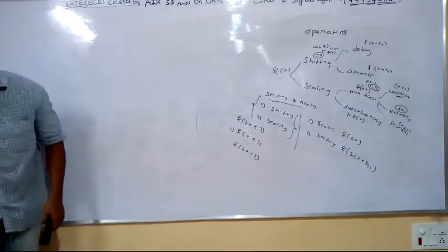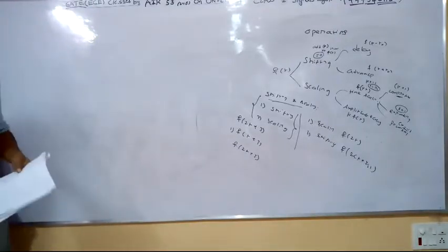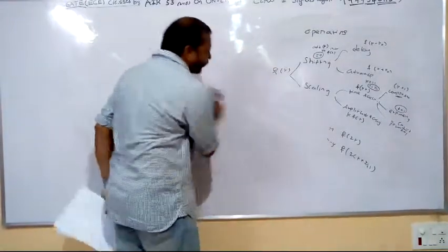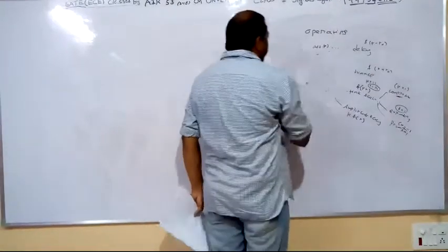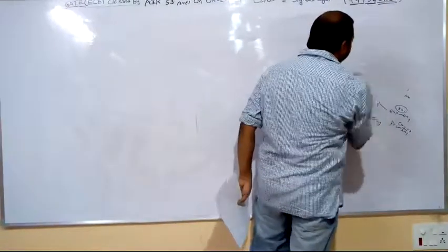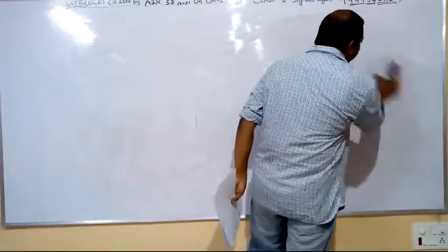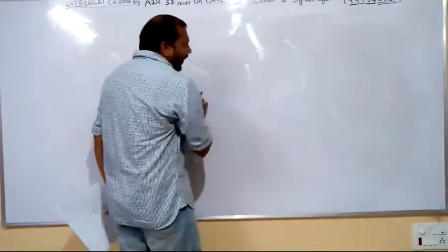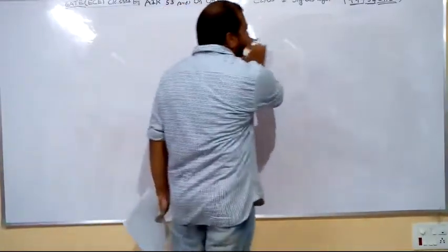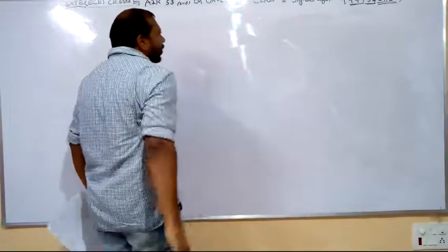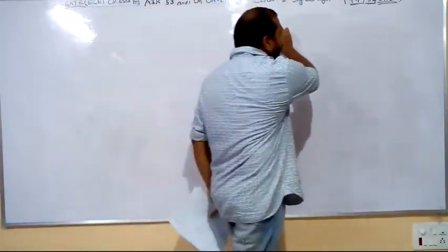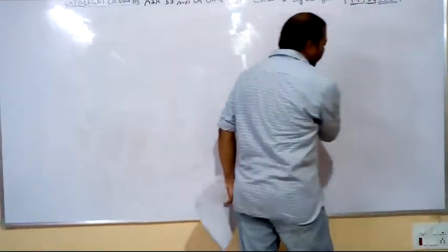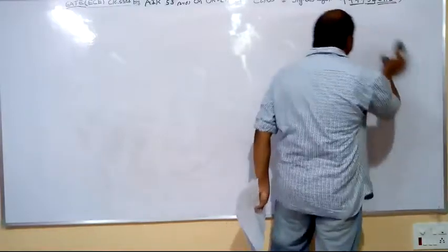Alright, we will analyze this procedure by taking some examples. Whatever the question, you have to follow the same procedure. If you already have an idea about this, the questions on this model are also over. For shifting, equate to 0 and add the corresponding t to each and every instance of the time. For scaling, equate that to 1 and multiply the corresponding t value to each and every instance of the time. If you have a combination of shifting and scaling, first do shifting, then scaling.